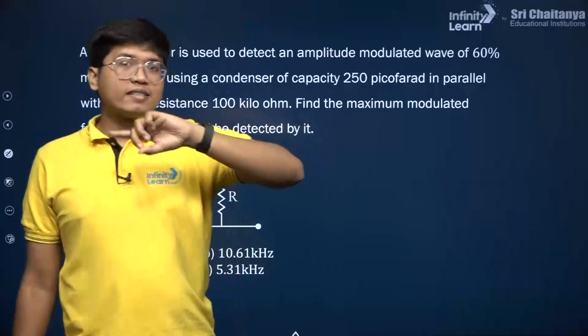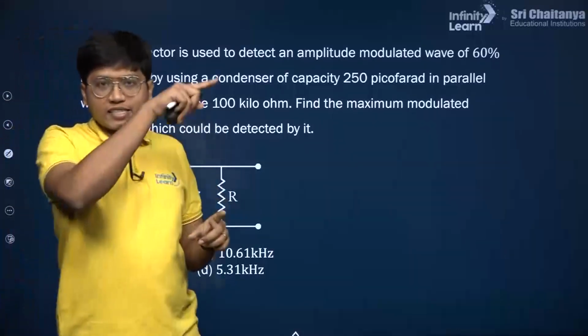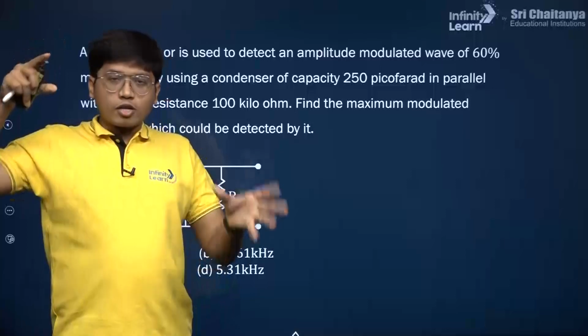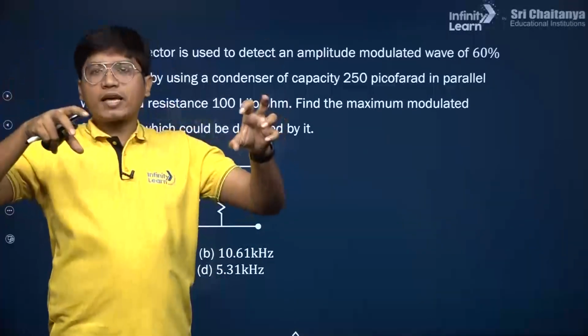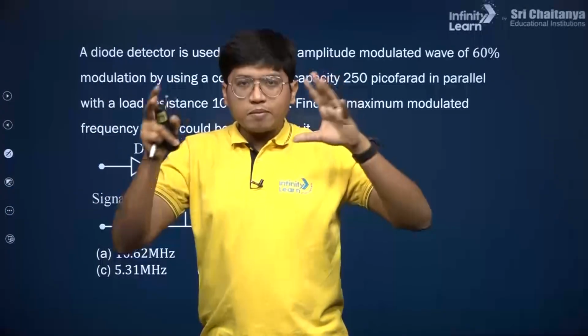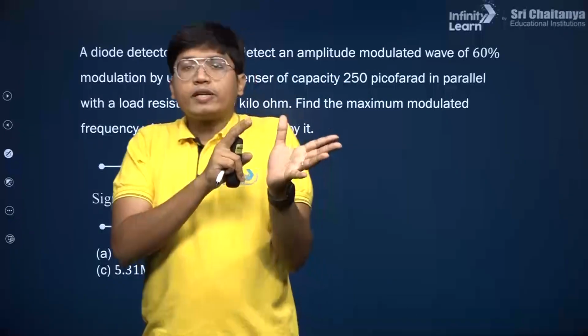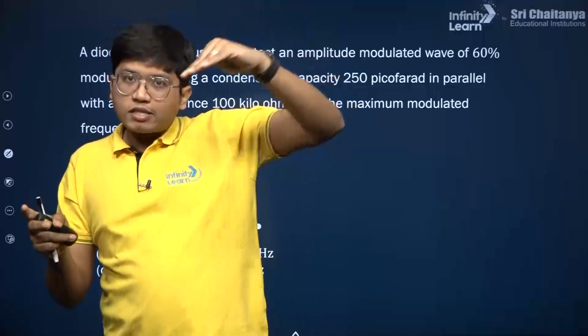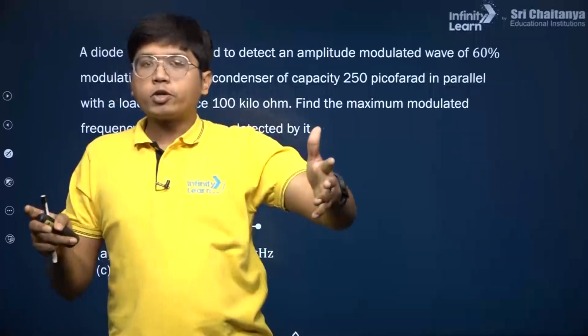Because they have that time constant, which means it takes time for the signal to die down, it takes time for the current to rise up. So if your incoming frequency is comparable to that, then you would get thrown off. You can't measure that, because did you get a peak or is it still going down slowly? You won't be able to detect it.